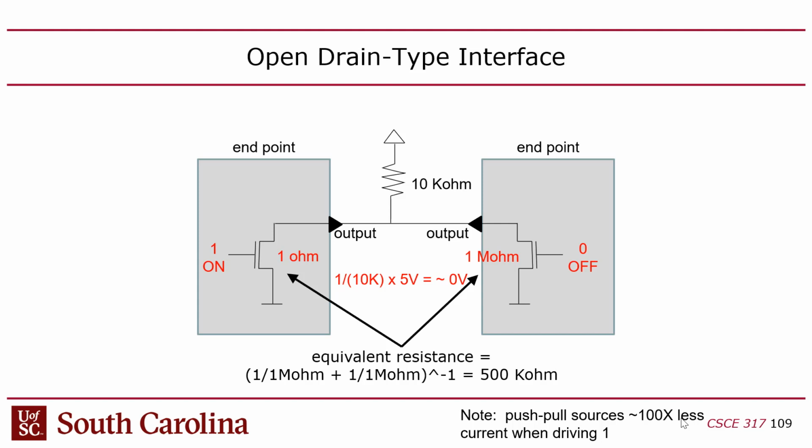So if I have the NMOS here and I turn it on, that's going to bring the resistance here from about a mega ohm down to an ohm or so, right? So it's going to connect. It's going to try to pull down the output to 0. So I end up there with a voltage divider that's 1 ohm over about 10,001 ohms. So that will effectively pull that voltage down to 0.